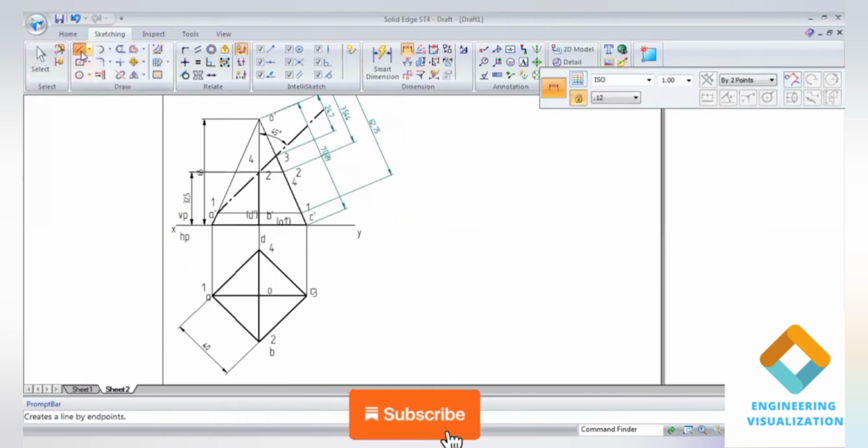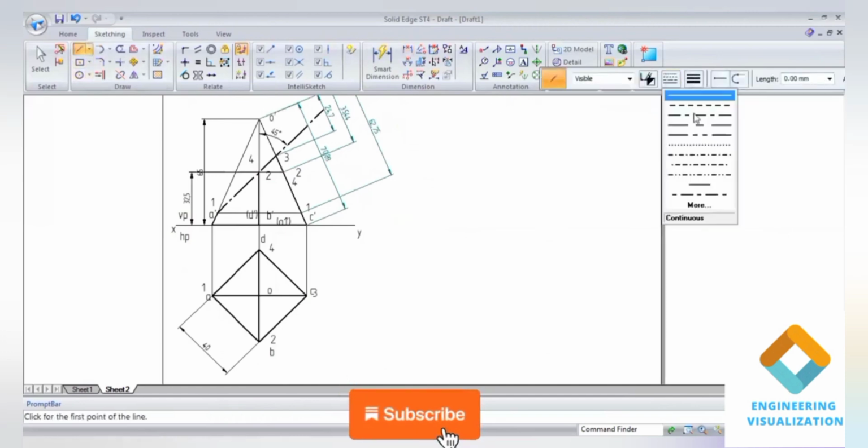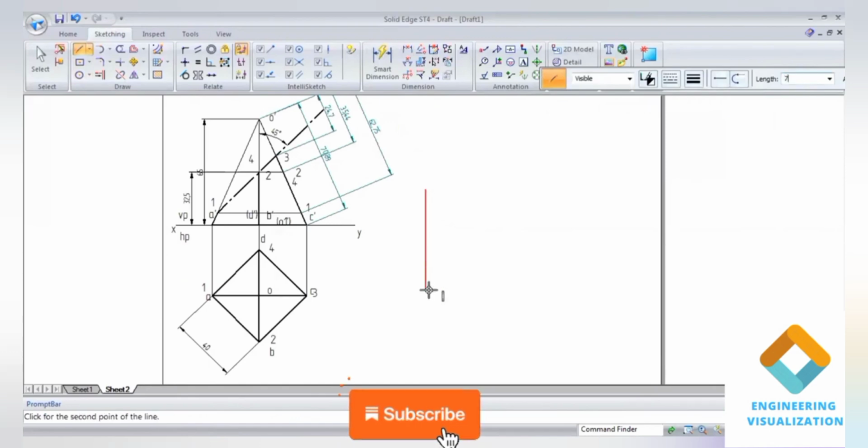Now we will construct the same slant edge length here. After drawing a vertical line, we need to draw an arc using the arc by center command. Use arc by center command here.